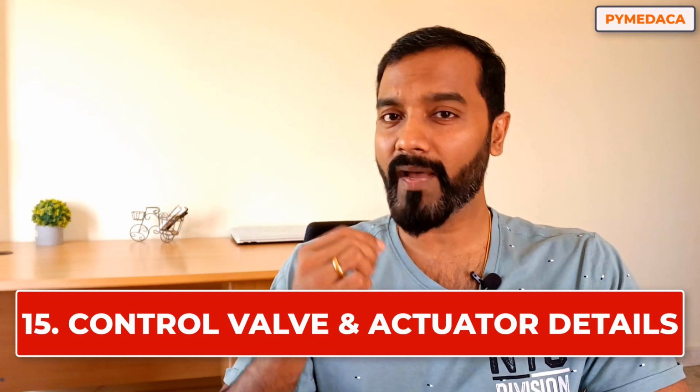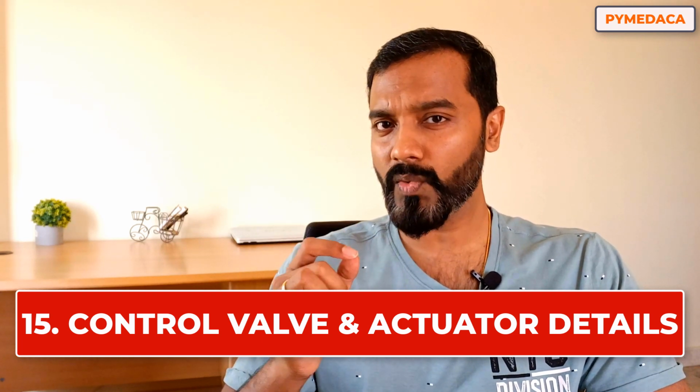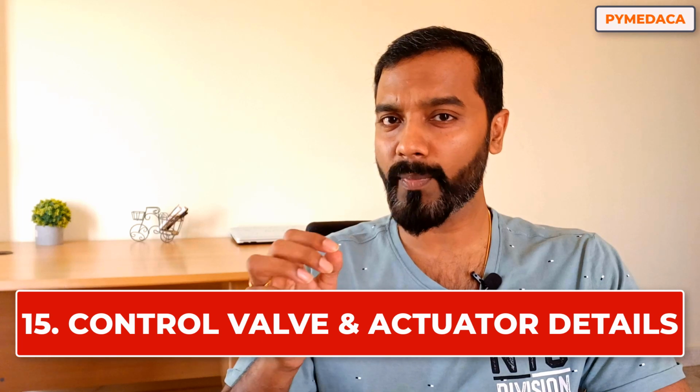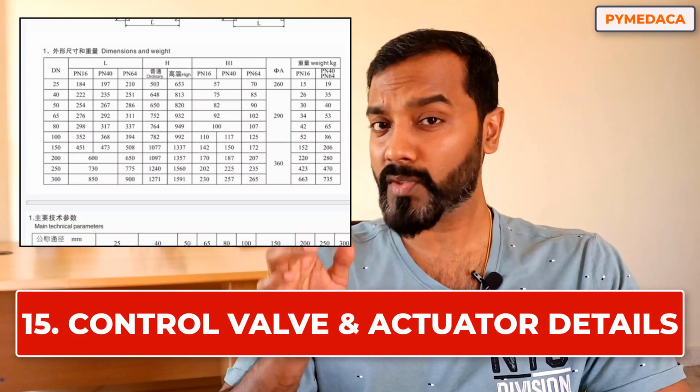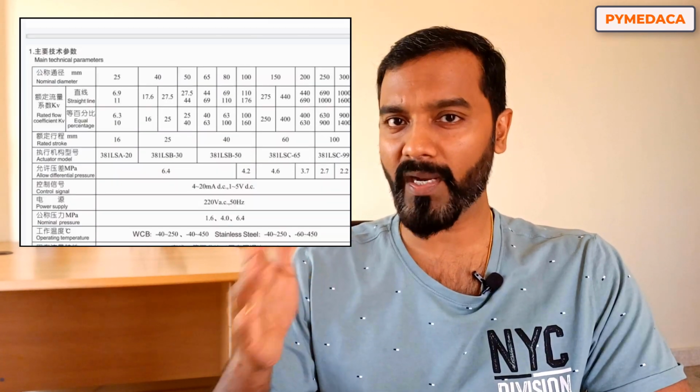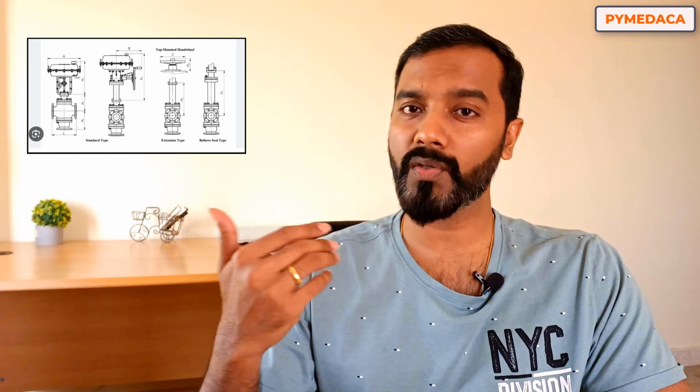The last but not least is the control valve and actuator detail. See, the control valve is considered a critical component in process piping, because it controls critical parameters such as pressure, temperature and flow. So generally the C&A or instrumentation team is the one who procures this. So the mechanical team does not have the dimension details of this control valve. Unless you know the dimension of this control valve, you will not be able to finalize